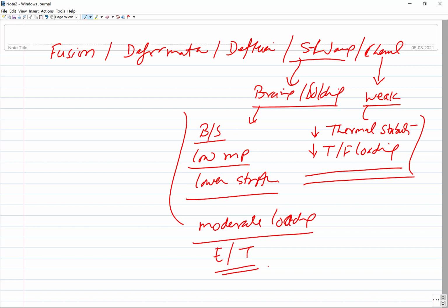these may be good enough. So depending upon the application and situation, we may use brazing or soldering, where there is no melting and fusion of the base metal. Little heat is supplied just to ensure the melting of the low melting point filler, which is used in the form of brazing and soldering.